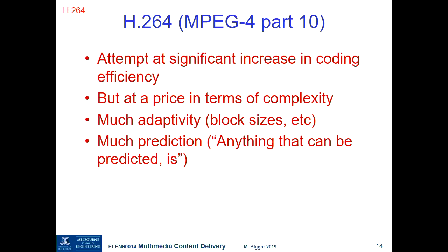Just thinking the best way to describe this. The objective was to have as many scan lines as possible because we want high vertical resolution. But we wanted to minimise the number of frames per second because of the limited bandwidth available and the limited processing that was available.